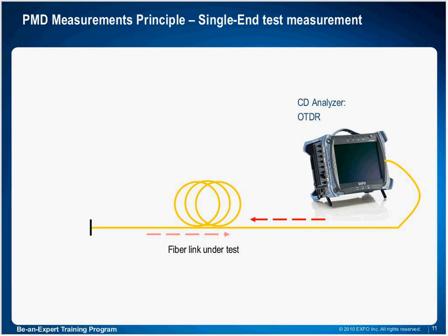Even at 1 kilometer or 2 kilometers, it is such a short length that the total amount of dispersion is not a factor. As we saw before, in a 40 gigabit signal, the tolerance is roughly 60 picoseconds per nanometer total. At 60 picoseconds per nanometer, you need more than 3 kilometers of standard single-mode fiber before you start to get close to that value. So it must be possible to test shorter than 3 kilometers, but it will not give you useful information, because not enough chromatic dispersion has accumulated.